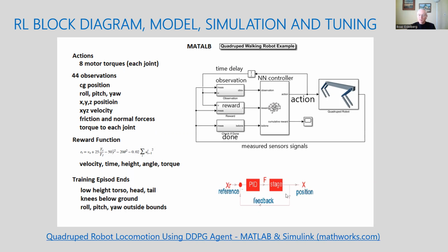There will be a controller, and all these feedbacks come into the controller. There will not be any reward function or any modeling or any observations anymore. It will simply be the multiplication of all these sensor signals times the weights of the neural network, and the output will be the motor torques.